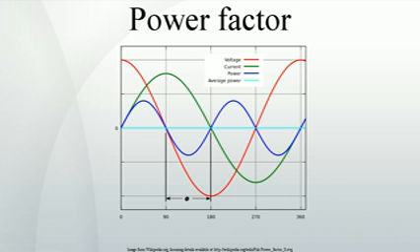In the case of a switched-mode power supply, a boost converter is inserted between the bridge rectifier and the main input capacitors. The boost converter attempts to maintain a constant DC bus voltage on its output while drawing a current that is always in phase with and at the same frequency as the line voltage. Another switch-mode converter inside the power supply produces the desired output voltage from the DC bus. This approach requires additional semiconductor switches and control electronics, but permits cheaper and smaller passive components. It is frequently used in practice.